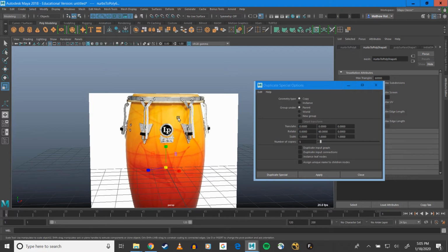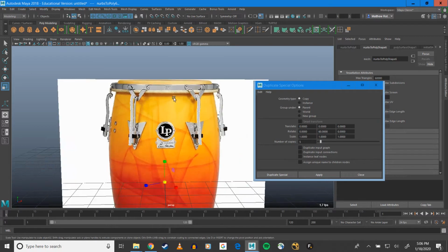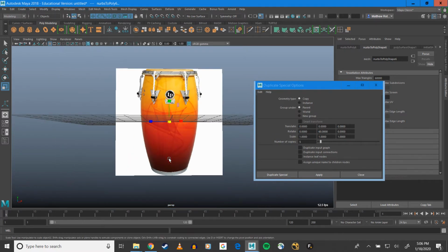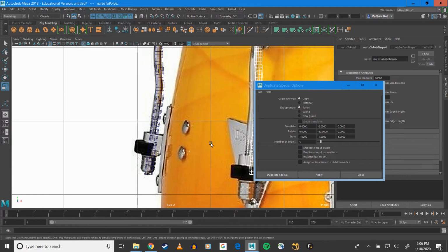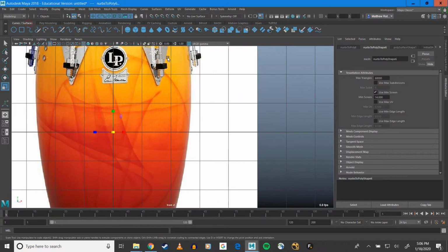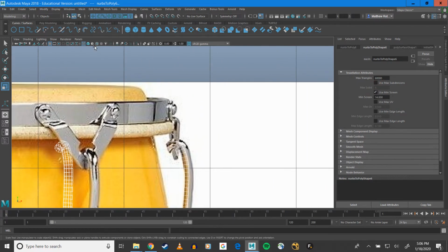And now I'm just going to use the Revolve Tool a few times to create this part of this band that tightens down the head, as well as the head and the base for my body. So, I'm going to go back into my front orthograph, and perhaps I'll just start with the band up here.